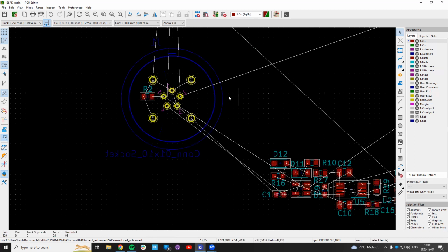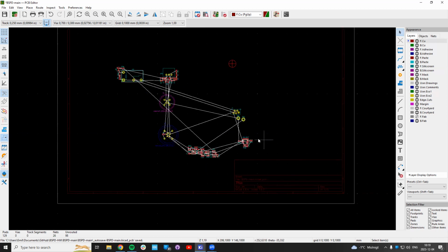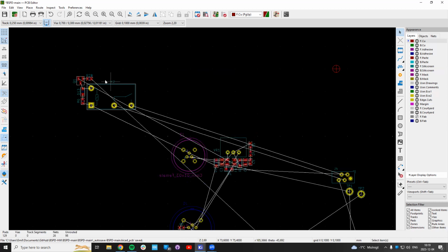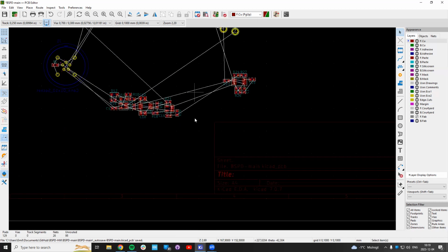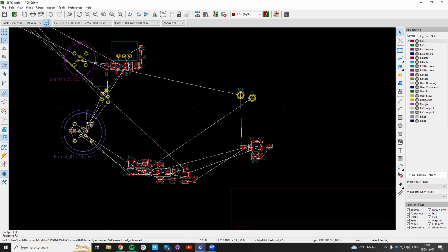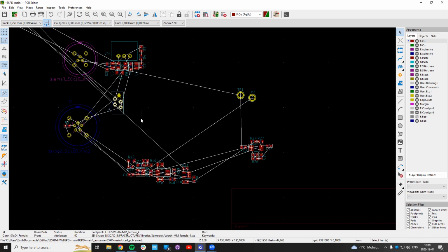Yeah, we'll keep it on this side. Yes, I'm pretty happy here. So as we said, we're only restricted by trying to make it small. So what can we do? Well, now it's just a matter of starting to place the components. I like starting off with the connectors and trying to get them in a place where, because they're usually the ones that take up a lot of space. So I try to connect them in a place where it would make sense to connect them to the other PCBs in the same compartment, or things similar to that.